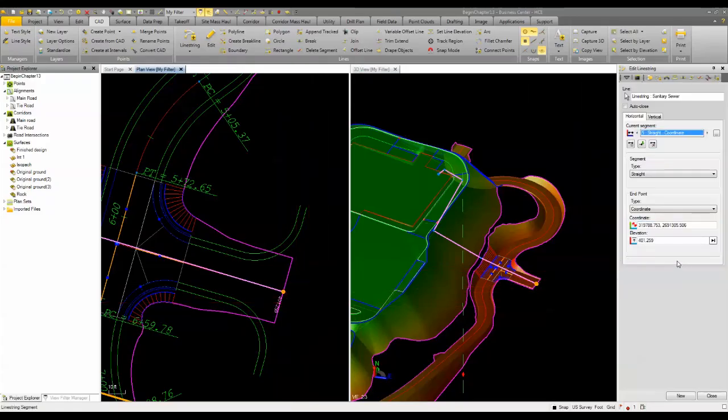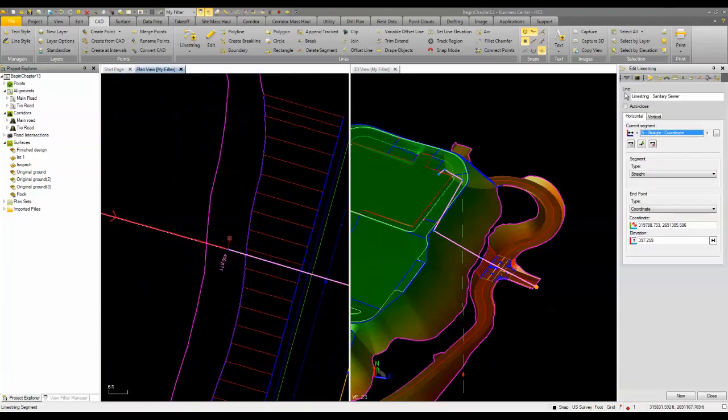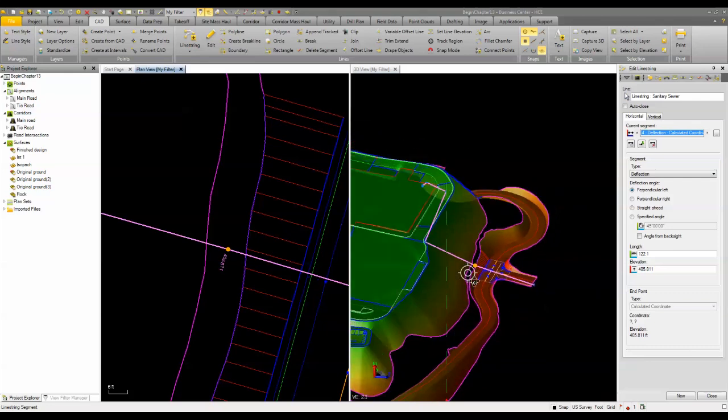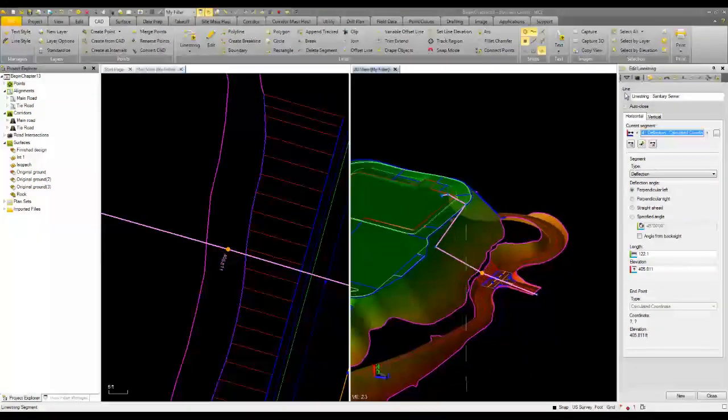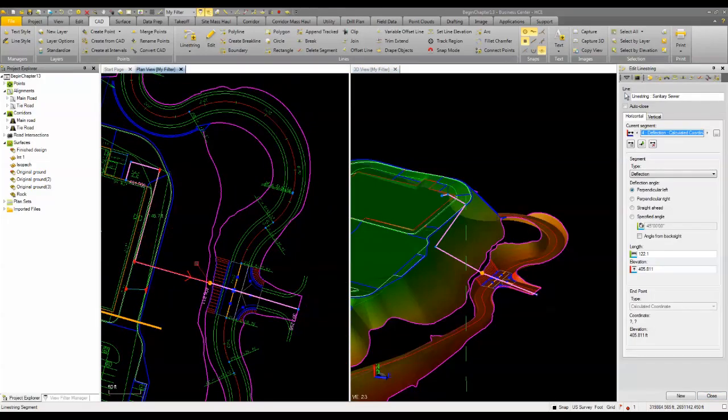Now we're going to cancel that, and we're going to kick this down 4 feet. We're going to come back over here, and we're going to kick this one down 4 feet, so we'll go -4 on that one, and we'll hit save. Okay, now you can see that we've got some work to be done on the vertical. All right, so we're going to work our way back. We're going to put in some minimums.